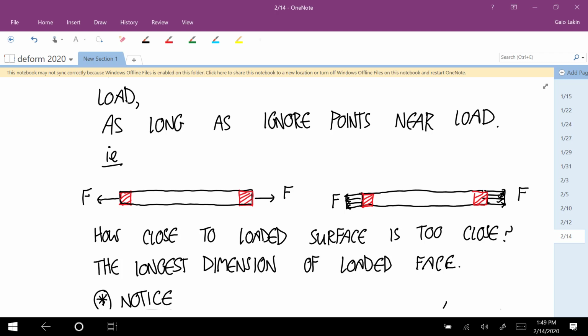What angle is that shear stress face acting on? Well, the answer is that face would be tipped 45 degrees because that's what you have to do in order to find the stress tensor with the maximum shear. And that actually has a practical application in materials that are really brittle.